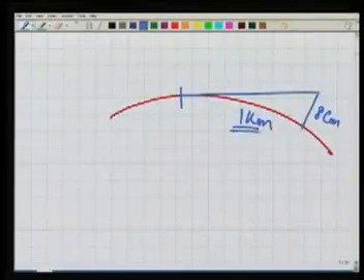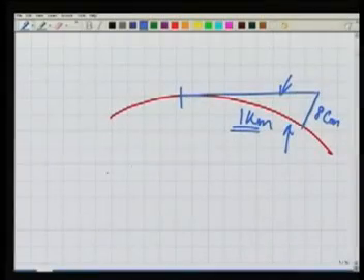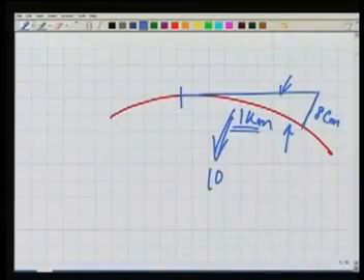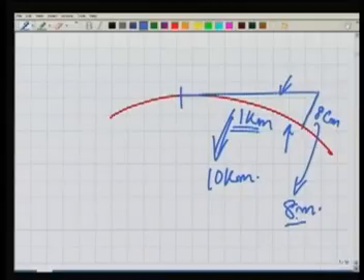Now let us see that. Well, we know this value. In a distance of 1 kilometer, the horizontal plane deviates from the general curvature of the earth by 8 centimeter. And if this distance is 10 kilometer, then this deviation becomes 8 meter, because this deviation is not linear, it is non-linear, and we will see also how to arrive at that later on.